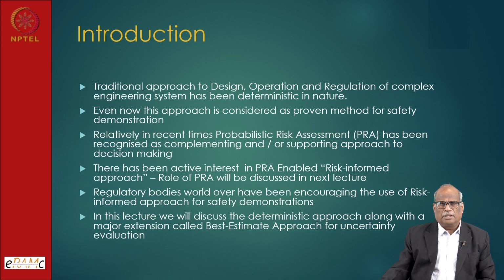Deterministic approach is providing adequate provisions in terms of protection, redundancy, diversity, design, and various safety factors, such that we are confident or we have determined that the unlikely or undesirable event, especially the design basis of the plant, is satisfied.